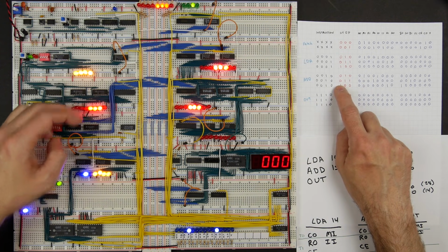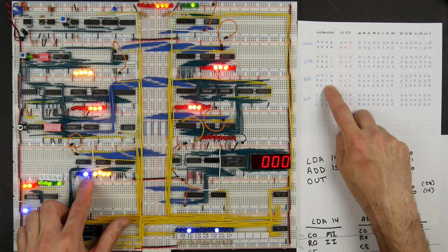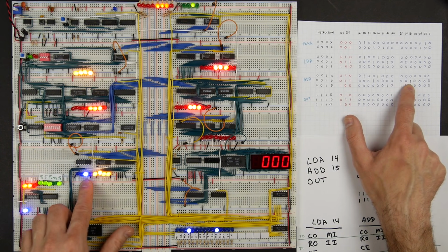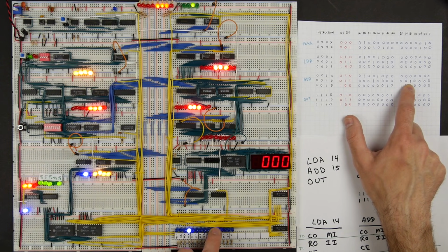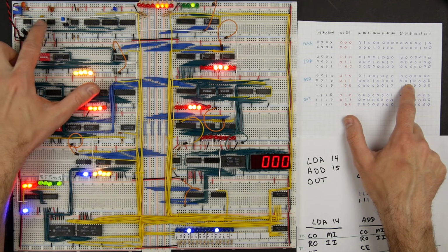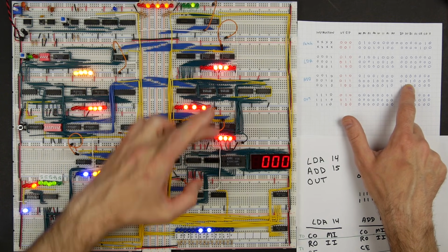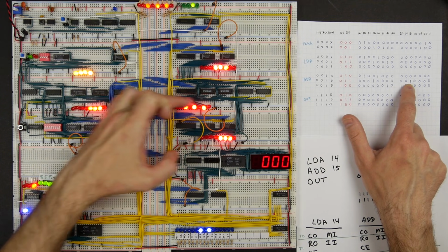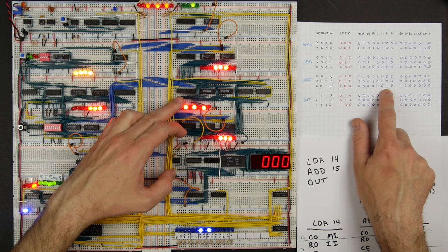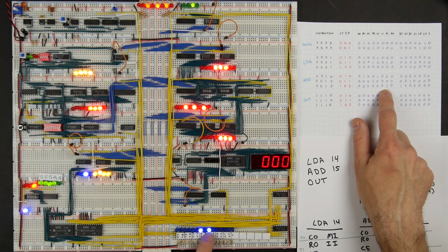So the next step here, 011 is the step we're on. We're still doing an add, because that's what's in our instruction register. So we've got RAM out and B in, and indeed that's what's showing up down here. So RAM out, B in, so it's going to put this 14 into the B register. And that's what it does. And now we've got the 28 in A and the 14 in B, so we get the sum over here. And so the add is then going to take this sum out and put it into the A register. And so that's in fact what we have here.